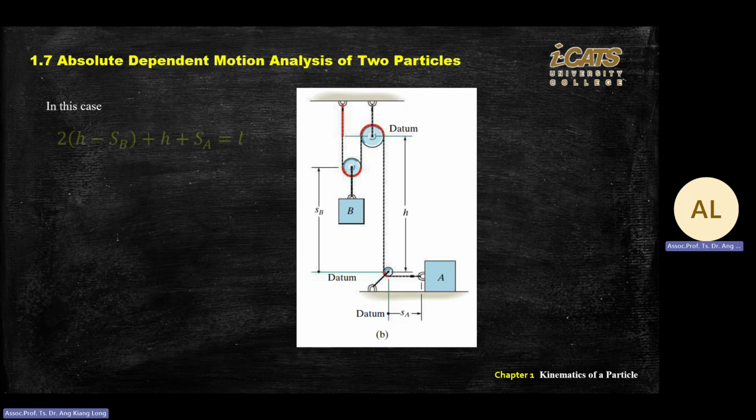Now, first step, always find the total length. Then you do time differential. You get velocity. You arrive at one equation. This is important. Get velocity. The next step is to write the acceleration. These three equations are important for pulley questions. Always start with total length. Then you do time differential. I want you to see the relative motion between two bodies, velocity and acceleration.